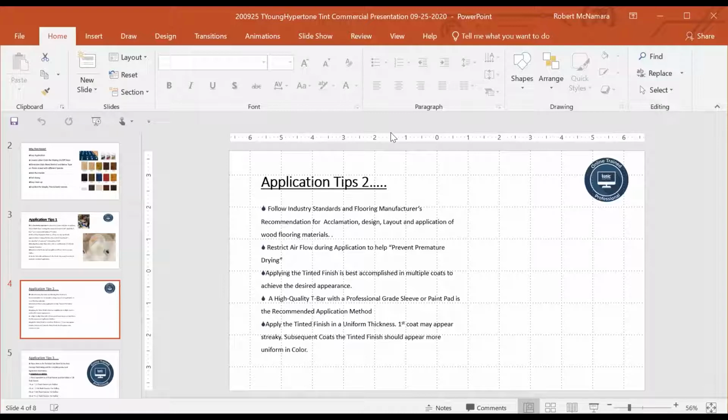It's going to be very difficult, when you're only tinting up to 10%, to get the floor completely covered and the look you're looking for with one coat. We typically see a 2-coat application is going to get you right where you need to be. The floor is going to come out looking really nice, and you're going to have even color, and it's just going to go much more smoothly for you.